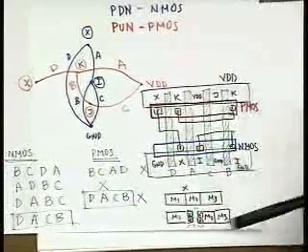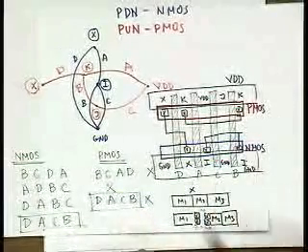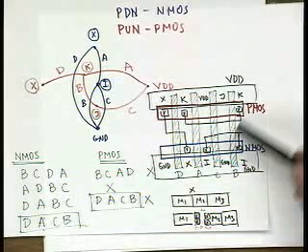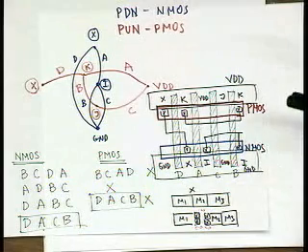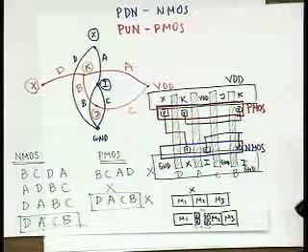Basically, you can almost do this all in one metal layer. You may need additional metal layers if you want to connect all these signals, but if you bring them from the bottom, then you don't even need to spare an extra metal. So that's basically the strategy, how you can create the highest density layout. And this is really valuable. People at companies would really like you to be able to do this.